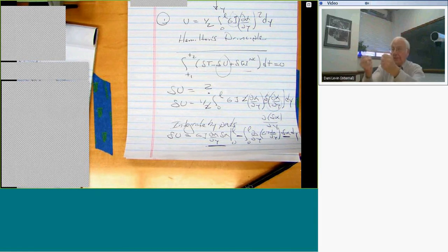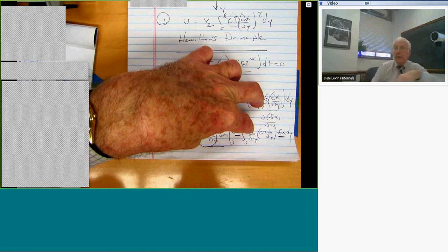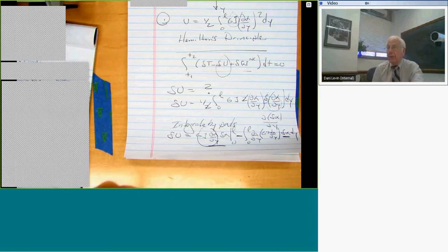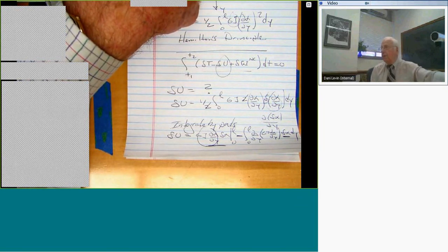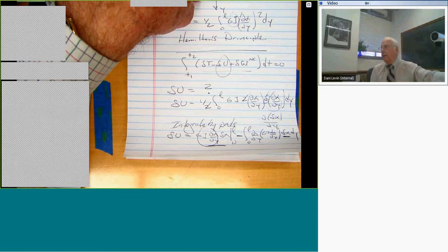If alpha truly is 0 at this point, then I can't make a virtual change, and I'm not allowed to do that. At this end, though, del alpha can be anything I like. Therefore, that term must be 0 at the end, which tells me that's the boundary condition, the one I was probably not immediately able to write down otherwise.